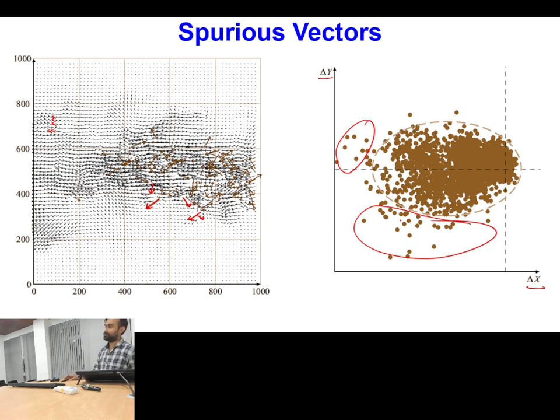So that's why near the interfaces the chances of getting spurious velocity vectors are more. Sir, how do we rectify these? By using some filters, meaning we remove the data. Yes. Sir, if we need velocity values there, not all data we will be removing. We will be identifying the bad data points and removing only these, not all.